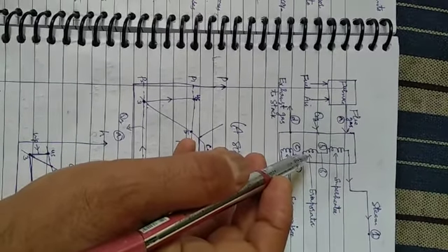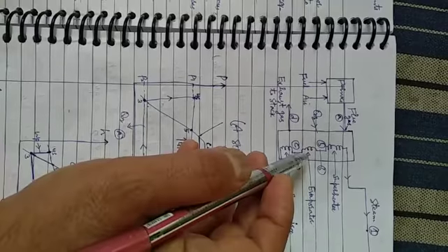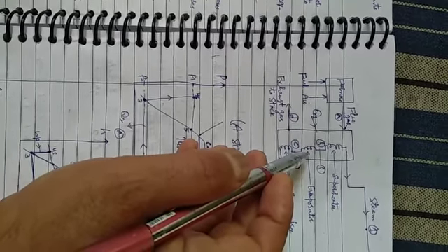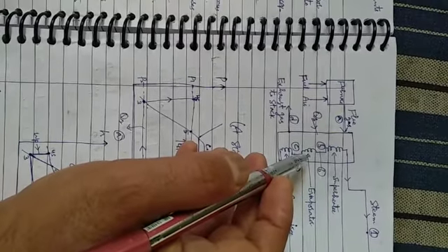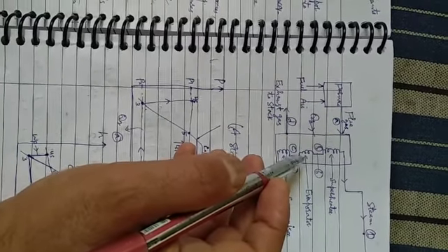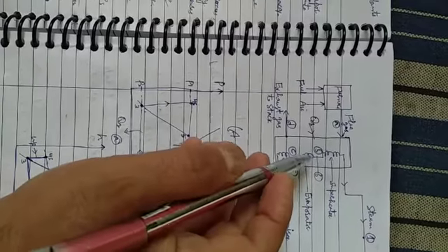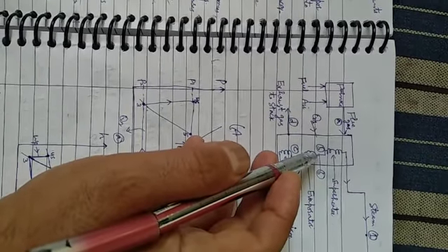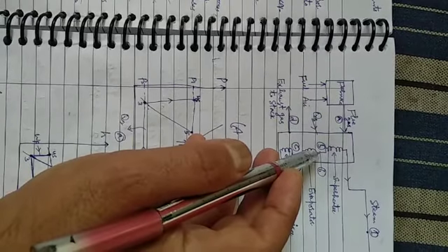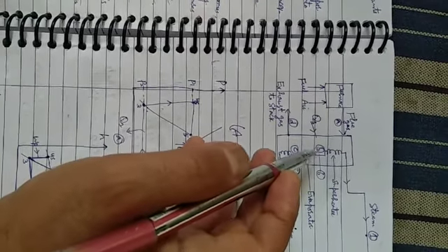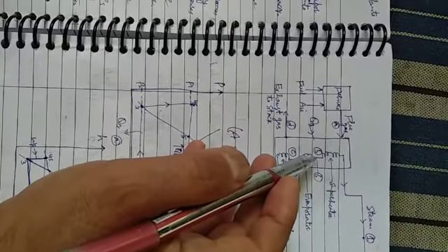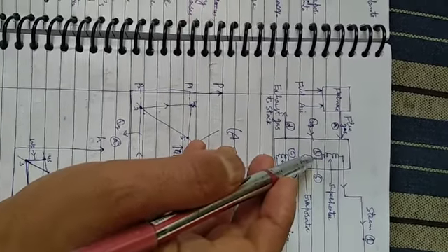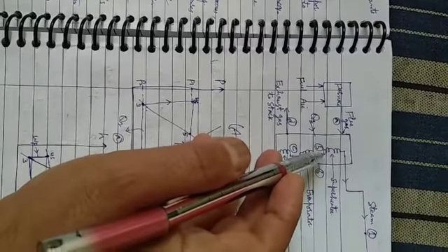After point 5, this saturated liquid enters the evaporator. Then what is the function of the evaporator? It evaporates this liquid into steam, but that steam is not actually the purest form of steam. It is also mixed with some water, so it is a mixture of steam and water. At point 6, it is also a mixed form of steam and water. So from point 5 to 6 it is evaporated, but the steam is not pure steam up to point 6.